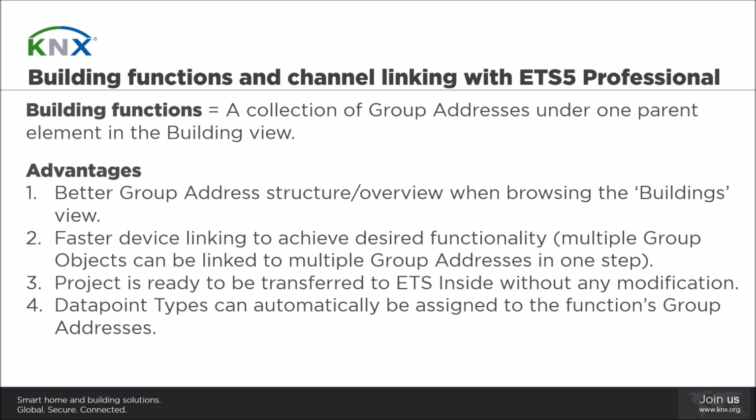From the technical point of view, a function is an element for collecting and structuring group addresses in a project, similar to what we saw for the group objects, but this time it is about the group addresses. So the principle is grouping group objects for the channels and grouping of group addresses for the device functions.